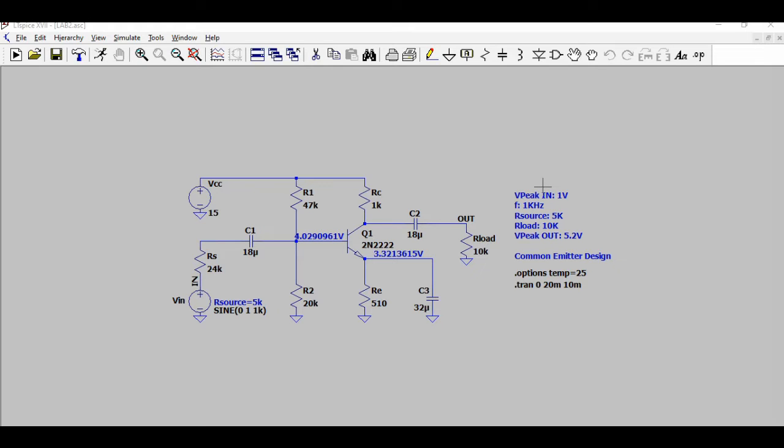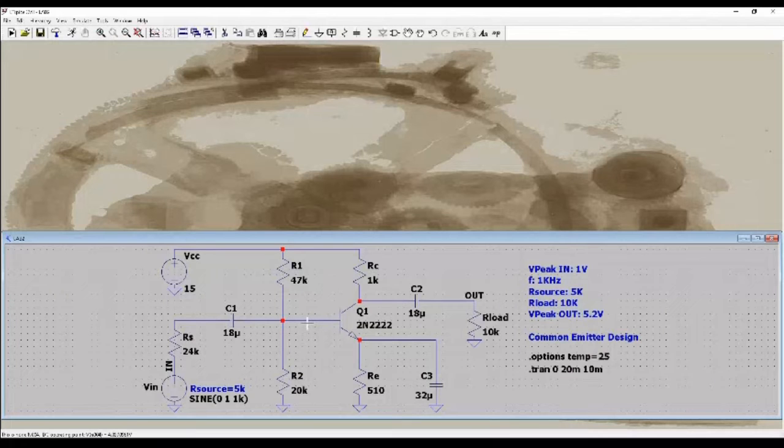We also review, according to the assigned conditions, the values we have: frequencies, input voltage, and output voltage, and this way we assign the corresponding values to the resistances and capacitances. Well, the input signal is applied at the base of the BJT transistor, and the output signal is located at the collector of the BJT transistor, as the amplifier is common emitter.